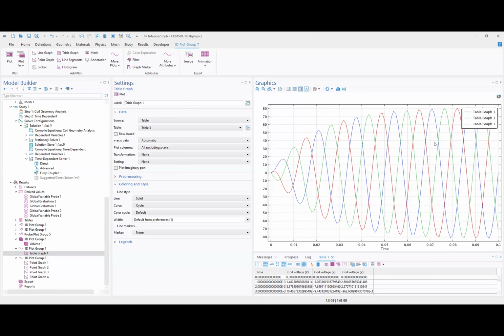If you have a time step that is too big initially, then the excitation may be too strong to start the simulation. But that's why I said that in the time solver settings, where it says output times, that time step has no effect on the actual time step.